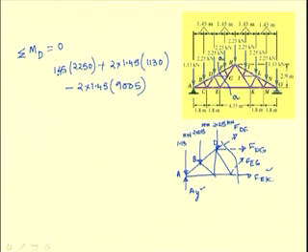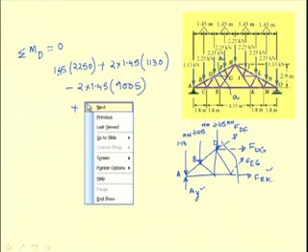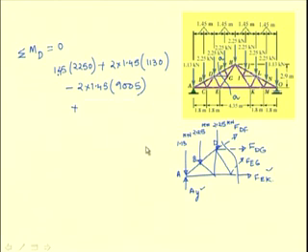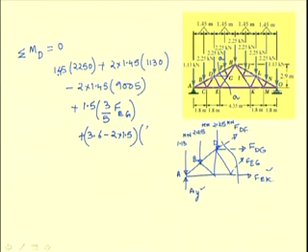is a counterclockwise moment. So, it is a positive quantity, plus 1.5 times the direction cosine of this force EG plus 3.6 minus 2 into 1.5 times the force in the member EG.